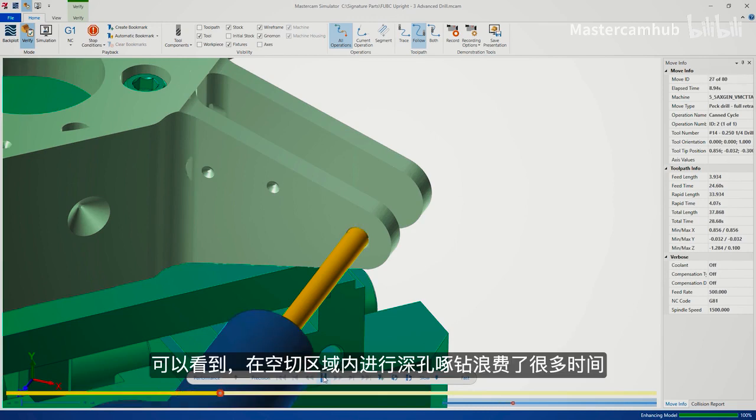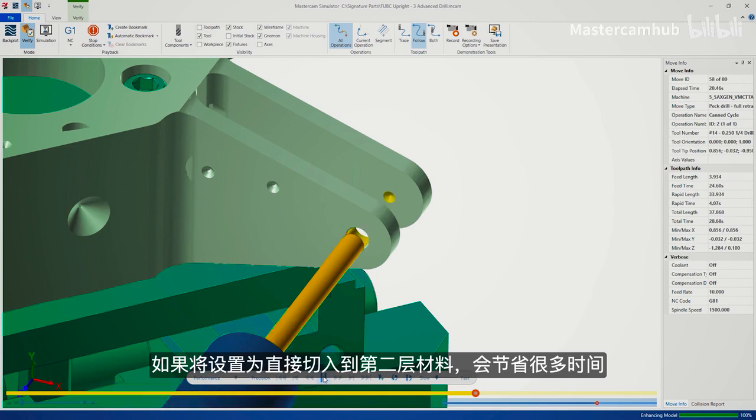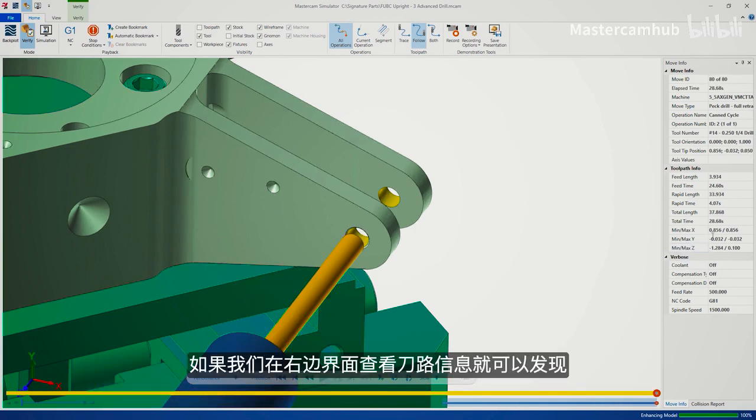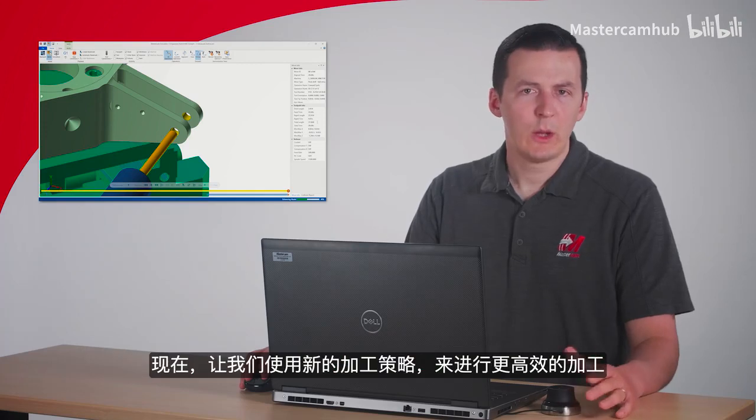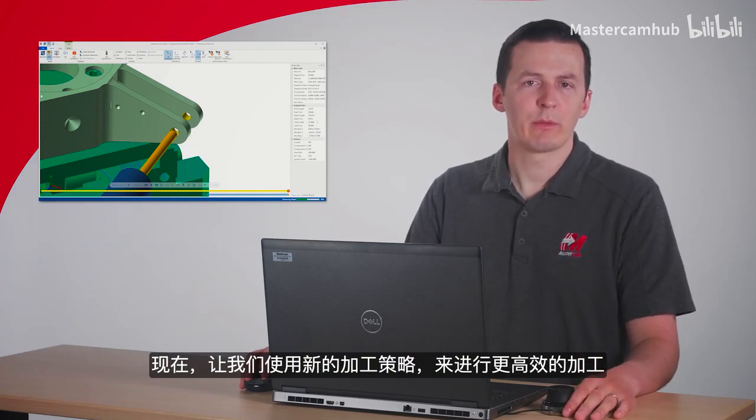Note how much time is wasted with the drill pecking in open air. It would be far more efficient for the drill to plunge to the beginning of the second layer of material. If we look at the toolpath info on the right side of the screen, we see that it took 28.68 seconds for this path to run, with the drill point traveling 37.86 inches. Now let's use some new tools to make this operation more efficient.